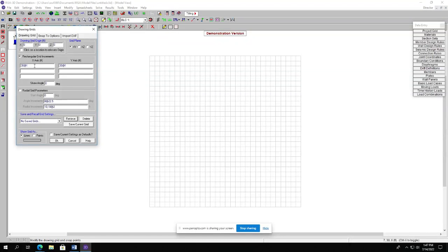For now I'm going to do a two-story building with two bays. So what I'm going to do is 20 feet, and you can write at the rate one, which means one bay of 30 feet. You can see the unit over here, but what I'm going to do is 20 comma 20. That means we will have two bays of 20 feet and 20 feet.